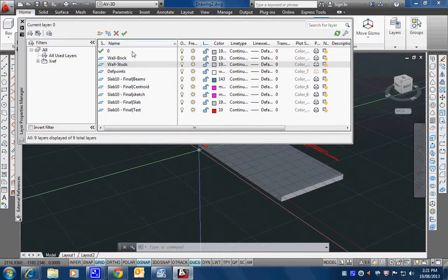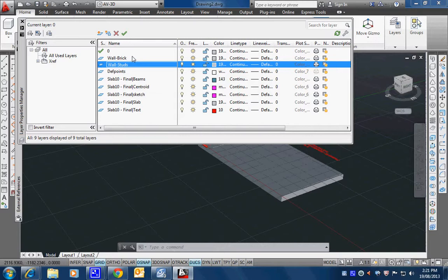It is a hierarchical system I'm using, and you can apply this to anything, whatever discipline you're in. The idea is that you're grouping same stuff together. So all the ceiling stuff might go into ceiling, or the mechanical stuff, or the site plan might go into site, or it might go into civil works or whatever. So just group stuff together so that you can easily turn things on and off.